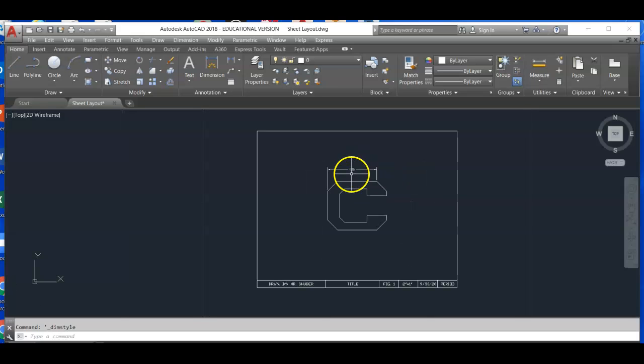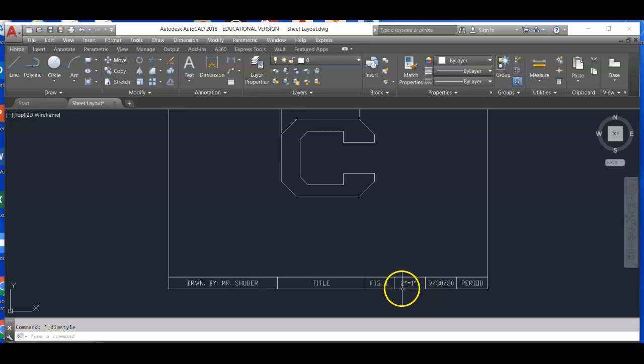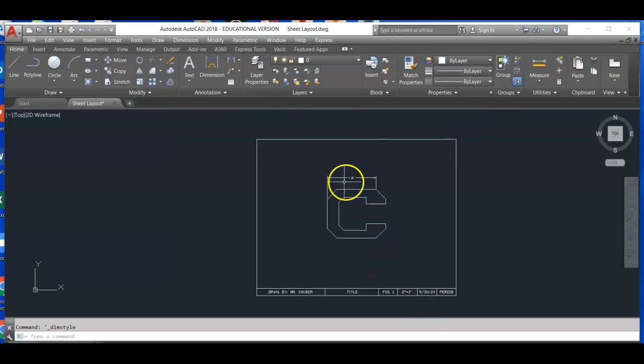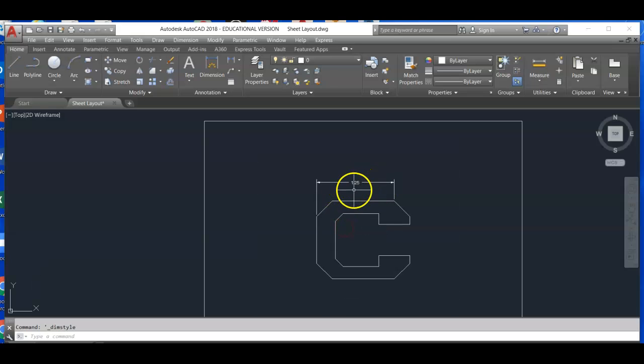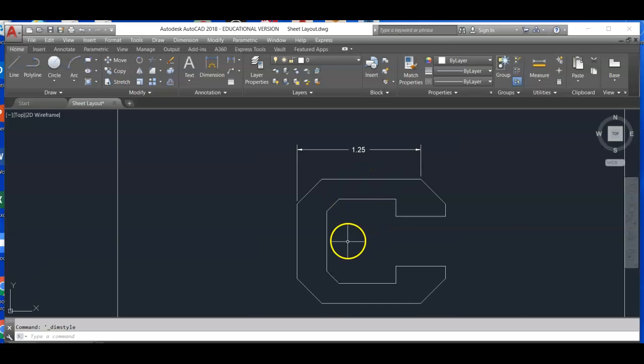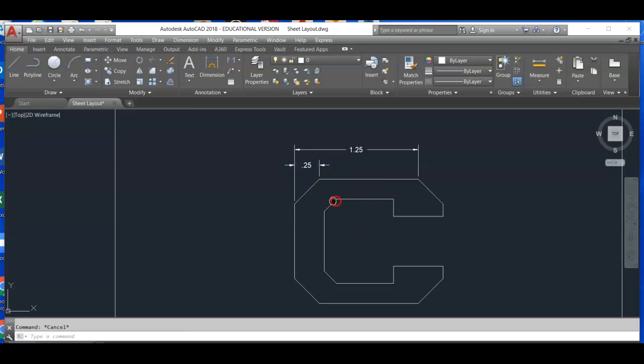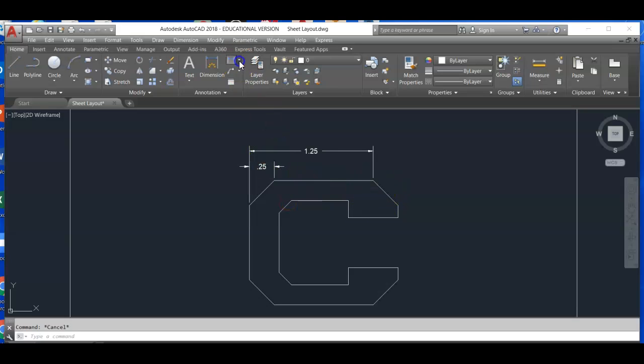Now, when we have it read like that, as long as down in your title block you have your scale set to double what it should be, then that tells the reader that it's scaled up. But this is the true dimension of what it should be. Okay? All right, so I'm going to continue applying my linear dimensions, snap from point to point. Let's see if this 0.25 goes inside. That's the way I'd rather have it, just like that. Now, on these angles, you can drop down.